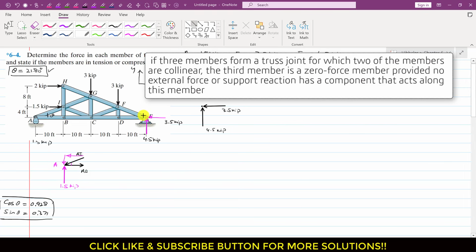and let's assume that this EF member force is acting away from this joint E, right? We are assuming both the directions as tension forces, right? And similarly, let's assume that this DE member force is also acting away from this joint E, right? So this is the DE member force, and this is that joint E under consideration, right? So this is EF and this is DE. So again we have that same theta here, right? So again we need to resolve this EF into its components. So it will have two components. It will have one component like this, and it will have one component which will be acting vertically upward, right?